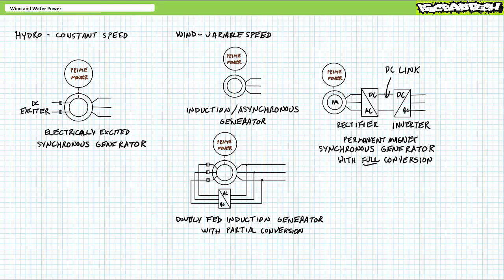And this wild three-phase AC is entirely rectified to DC and then inverted to grid-compliant three-phase AC with a proper magnitude, frequency, sequence, and phase shift suitable for export by a power electronics device known as an inverter. We'll take a look at some of the power electronics devices that make this possible in greater detail in later lectures.